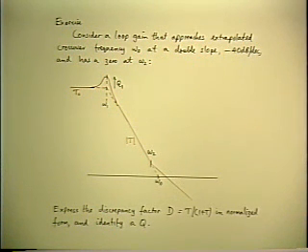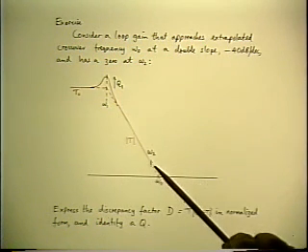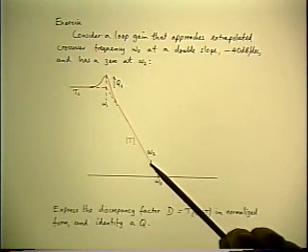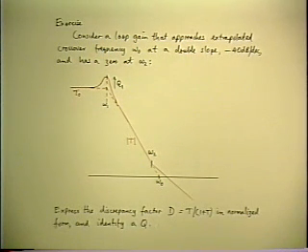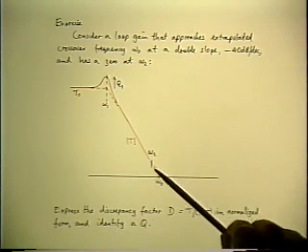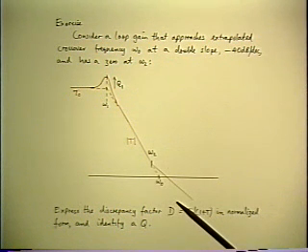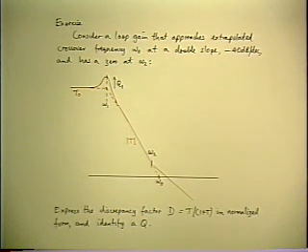And then when they started buying the capacitor from a different place, the ESR was lower, and the zero moved out, so they didn't have as much stability margin as before, and moreover, ESR goes down as temperature goes up. So at high temperatures, the corner moved even further out, and sometimes it moved out far enough that the stability margin went away altogether, and they had an oscillator on their hands, and an unhappy customer.